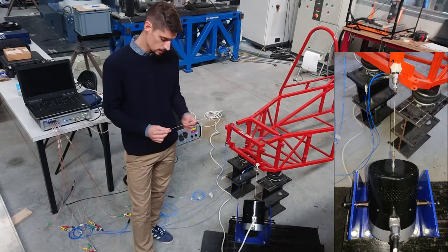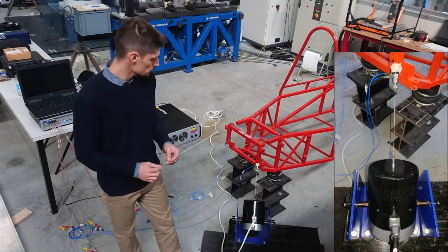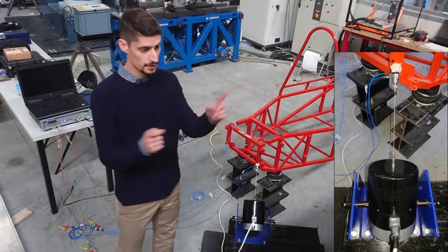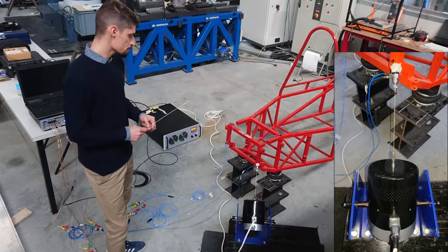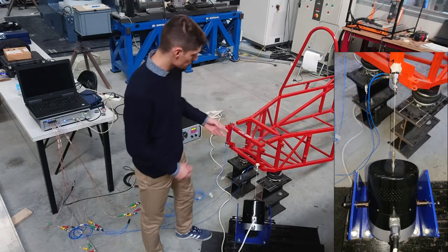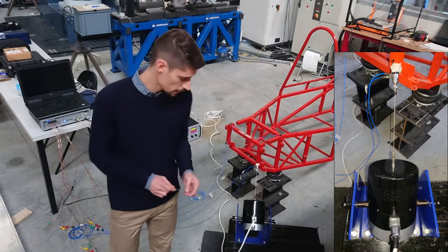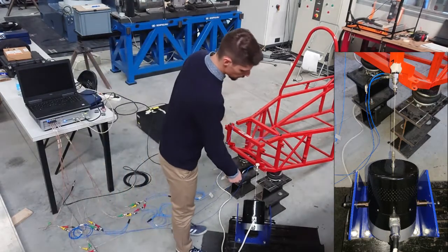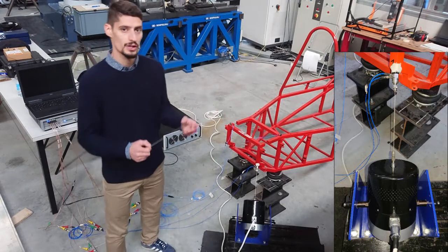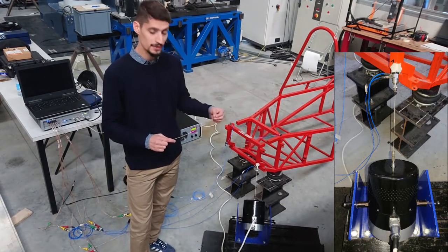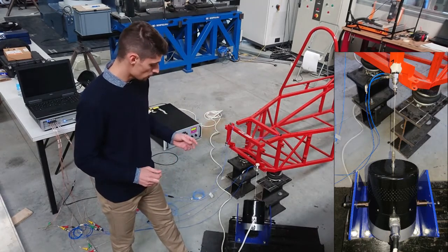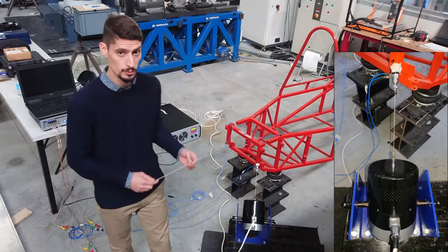because if the stinger is too long, insufficient force will be transmitted to your structure, probably without covering the entire frequency range. Instead, if the stinger is too short, the structure will be less decoupled from your shaker, and you could introduce the dynamic of your shaker into the dynamic of your structure. Therefore the stinger is set up to be as long as possible to maintain lateral flexibility, but still short enough to transmit the axial force without buckling.